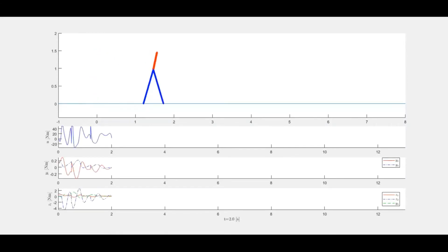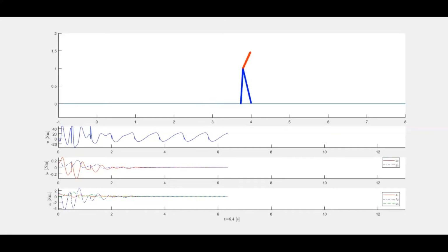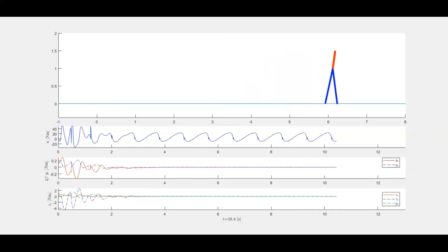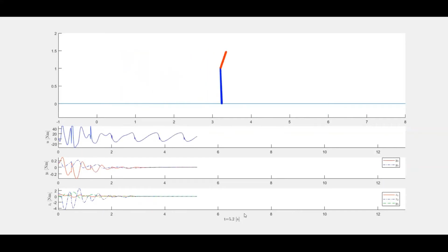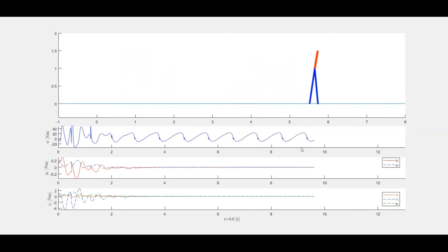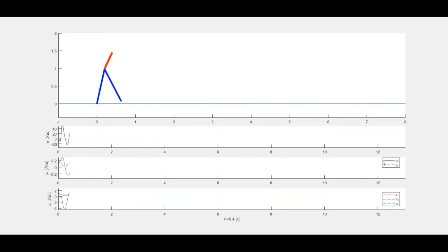So we started with some perturbed initial conditions, and a few steps later it converges, and we see that here the transverse coordinate y goes to 0. Likewise, the transverse coordinates zi, which are defined in the paper, you can have a look at them there, go to 0 as well after about 3 seconds. And we see then that the robot walks smoothly and well.